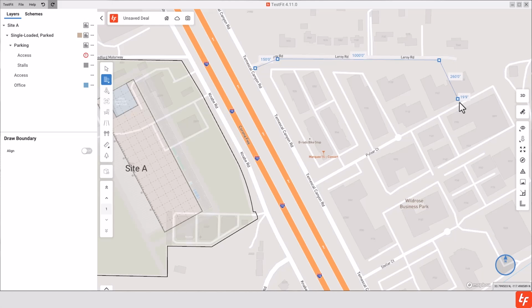There. Now if I wanted to make sure this next sight line is exactly 90 degrees with that previous sight line, we can enable the aligned drawing mode. So I can toggle that option right here. I can select it right here, or I can type A on my keyboard. And now in Canvas, my mouse and that sight line move in intervals of 15 degrees. So you can see how it's a little bit more jagged than before.